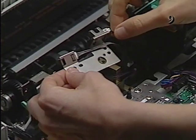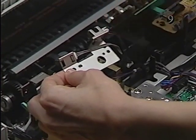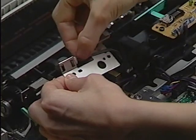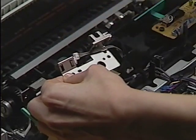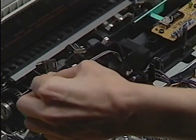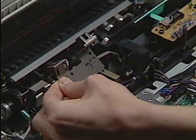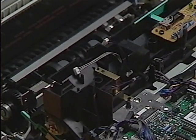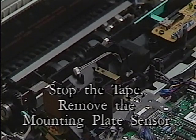Then disconnect connector J13 from the paper delivery sensor PS12. Disconnect connector J12 from the toner cartridge detection sensor PS11. Finally, lift the mounting plate sensor out of the printer. Stop the tape and remove the mounting plate sensor.